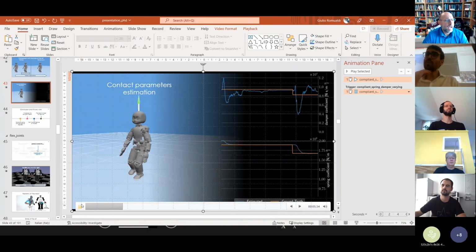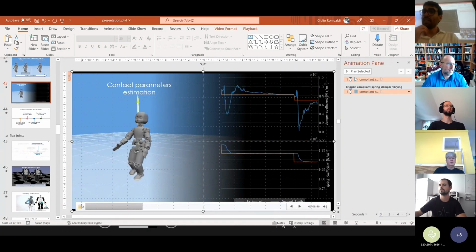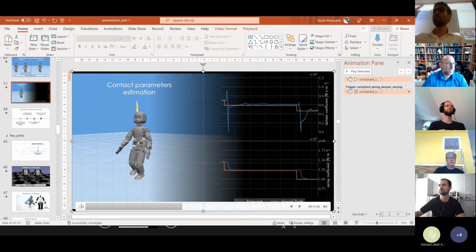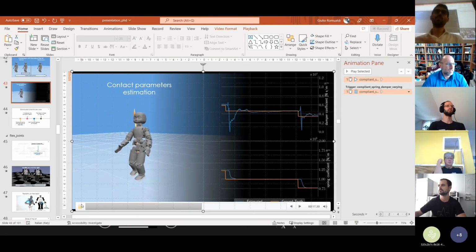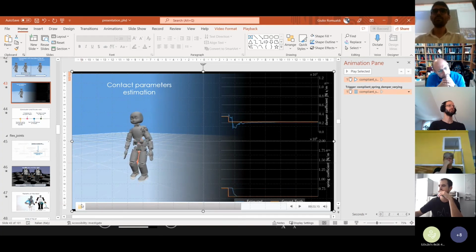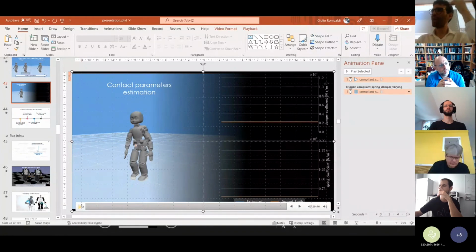Okay, so also here, there is a task for the angular momentum, but this task is generated from the inverse kinematics above. The inverse kinematics that I showed you, actually the one that we use for running the experiments on the real robot, has been run, say, in the case of stiff terrain, and then we use it as a trajectory reference for the angular momentum. So also here, we don't try to minimize the angular momentum, and the angular momentum that is generated is the one that generates the motion of the robot in position. So that's the reason why we don't have that kind of motion.